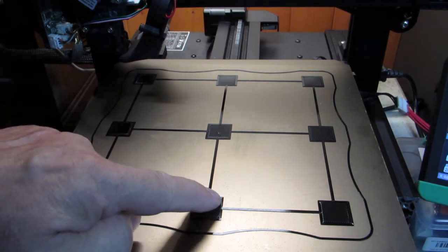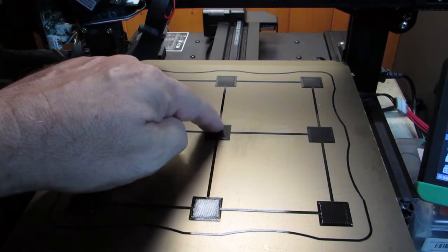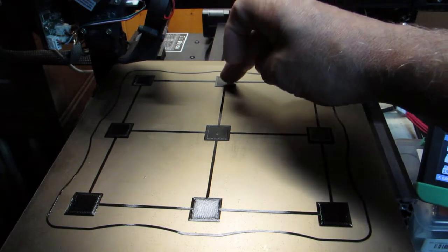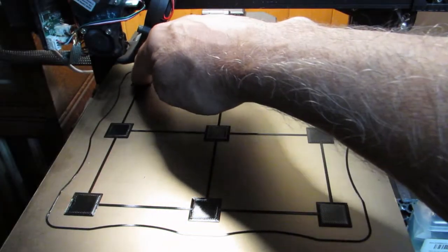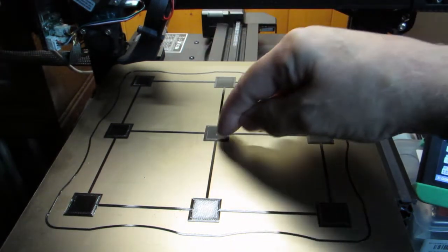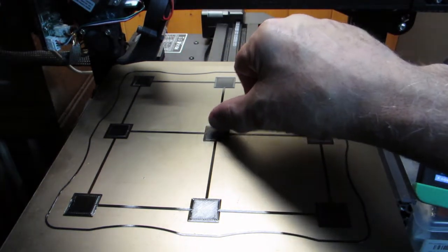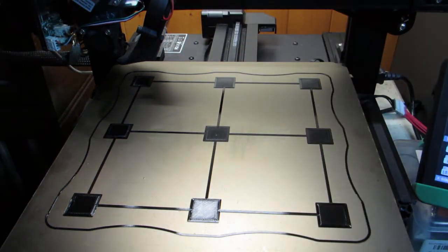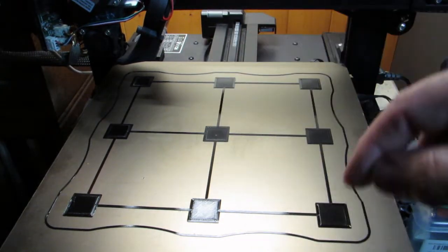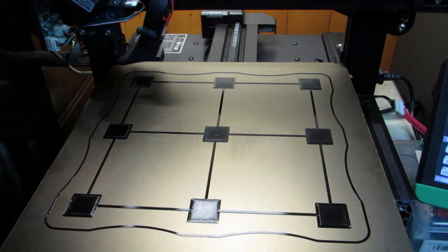So, camera's looking at glare on that pattern. Alright, so there are no lumps in the center of these squares the way there were in the center of the verification pattern circles. I think that's a consequence again of I'm drawing squares here, not circles. There's no reason to leave a scar. I can see the scar on the bed reflected in the print here. God bless, plastic has molded directly into that little hole and left an artifact there, so I can't use that as any indication of problems. I don't see any bonding issues on the lines.